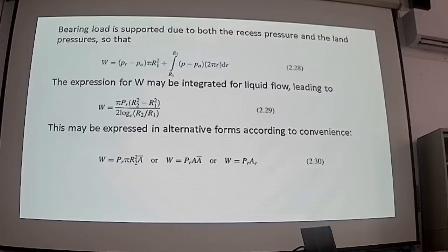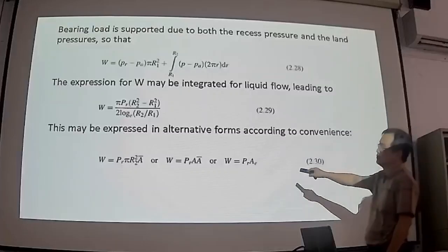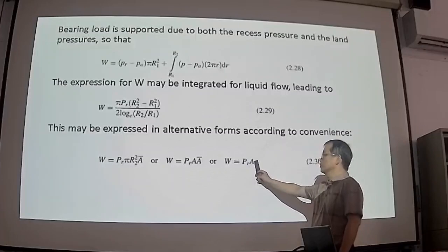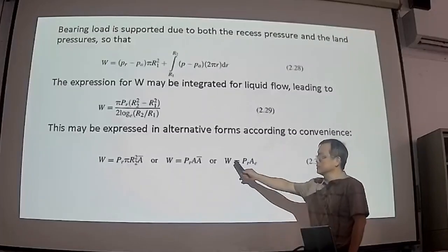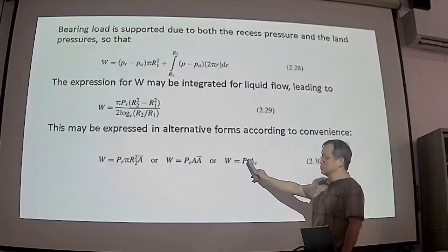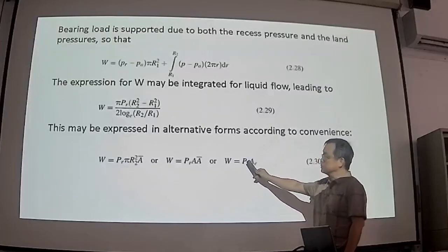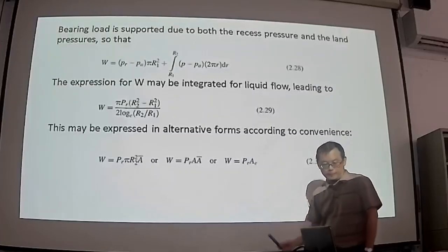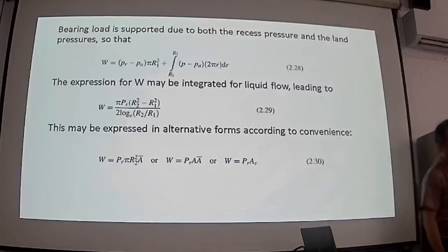Actually, it's the same equation I wrote before. The load capacity equals the recess pressure multiplied by the equivalent, or effective, bearing area.